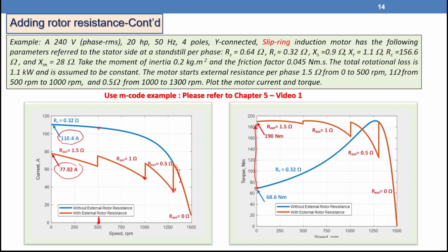I mentioned in the previous slide that this solution I don't recommend, but some people like to use it for high inertia loads, something like cranes, hoists, some elevators. So you can have a high starting torque. If the losses are not your concern, you can use that one to have a high starting torque, as you can see here. You push that one almost 3 times.